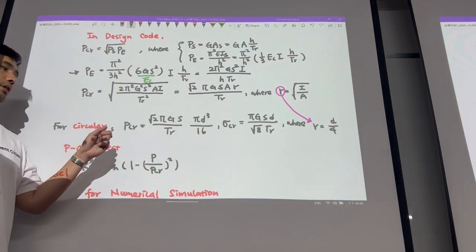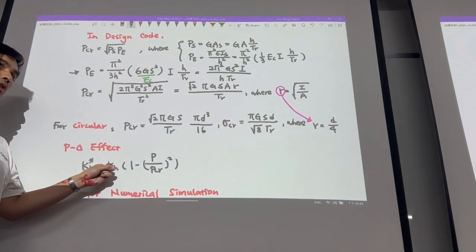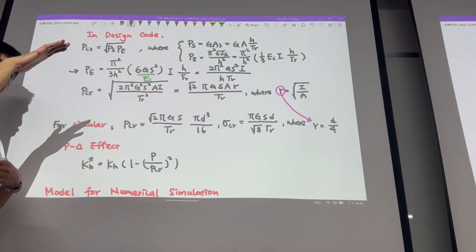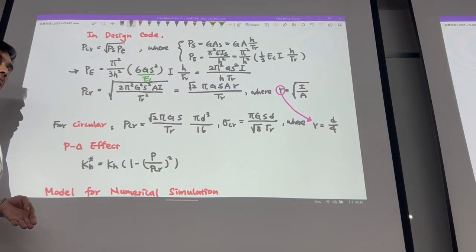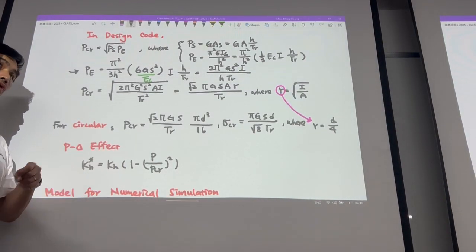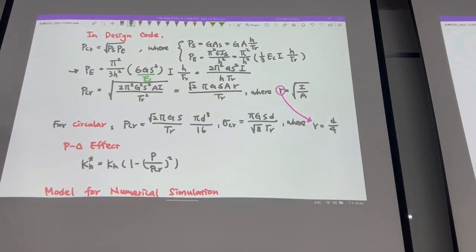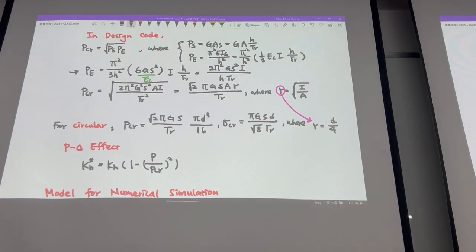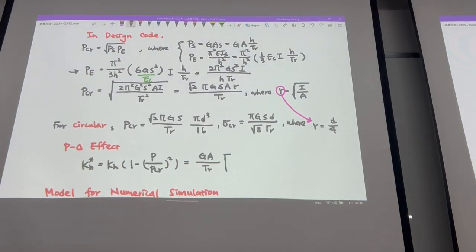If you squeeze your tofu, you may change that horizontal stiffness, right? So that equation is just like here. KH is without any force you apply. When you apply the force, then you will reduce the horizontal stiffness. Your KH is GA divided by TR, and for the rest of them, they are the same.